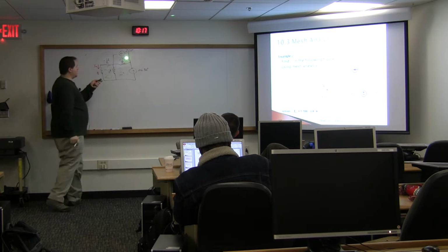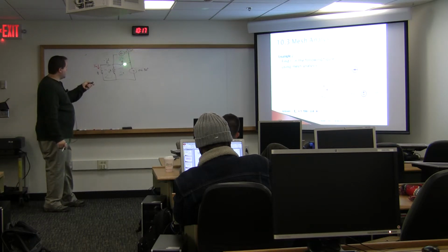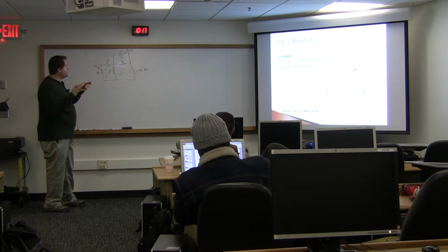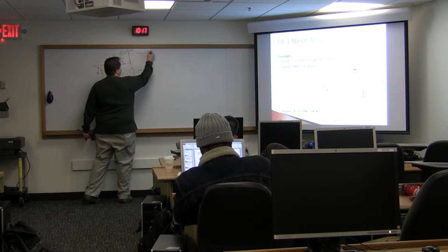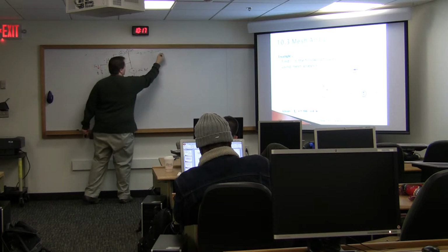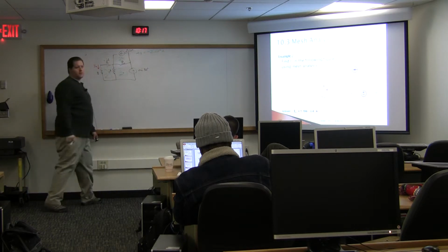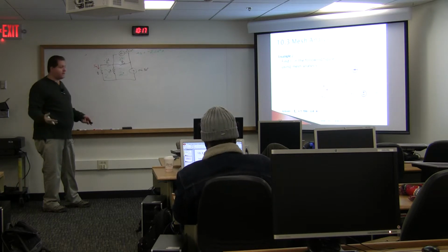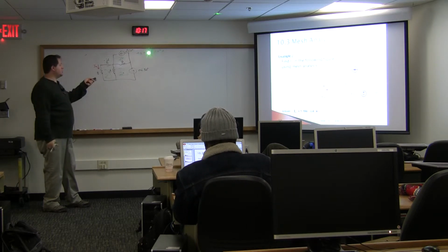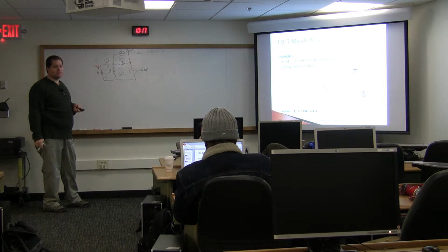But what is I3 equal to? Well, I3 is going clockwise, as all mesh currents should. We try to maintain uniformity going clockwise, but that's the opposite direction of this. So that means I3 equals negative 2 amps with a phase of 0, which we could also write as 2 with a phase of 180 degrees.